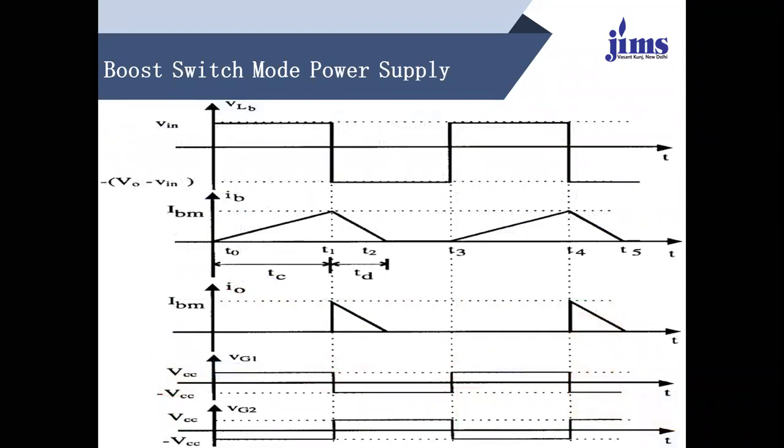First of all, we will discuss the waveform. Over here, we find that the input voltage, the on time and the off time we are keeping constant. Then we are observing the voltage over the inductor and the current which will be flowing over here. In this case, we are opting for a discontinuous system.